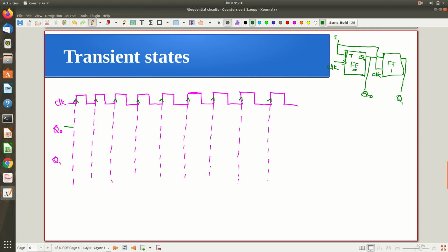It's supposed to toggle, but the input must be reflected at the output, so even though the clock triggering happens, the output does not toggle immediately. After some small amount of time the toggling will happen. Why that small amount of time? That is the delay for processing the input to the output. The flip flop takes the toggling input, the clock and the present state, everything, then analyzes it and changes the state.